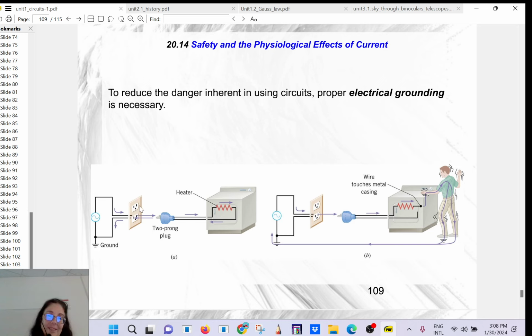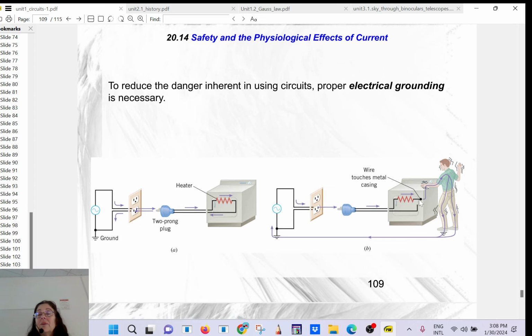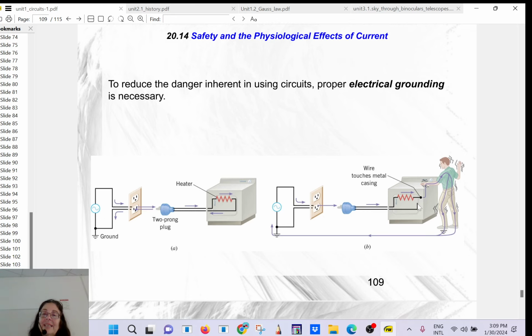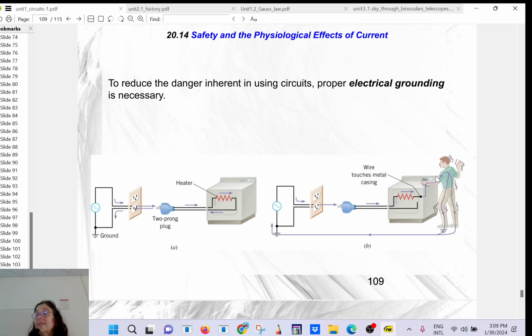Okay, so don't put anything inside. What's happening here is that you are missing the connection to ground. If there is a wire that is cut inside, it can happen, because mice or rats can chew on wires. And because you don't have the connection to ground here, you will be the return path. Remember, in a house, the return path is through the ground.